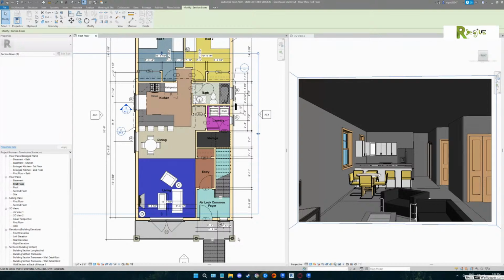The trick is people think that they can stretch the crop boundary on that perspective view. What you have to do is dolly your camera out of the room. Think about how they made sitcoms and things like that. They only had a house, half a house. It was a section cut into it. Which is another thing you can do.